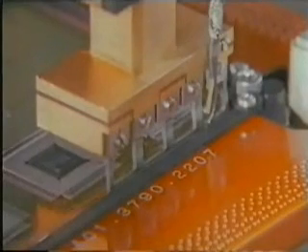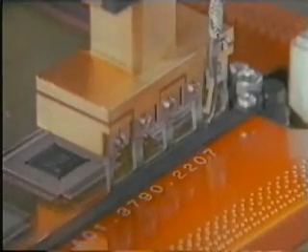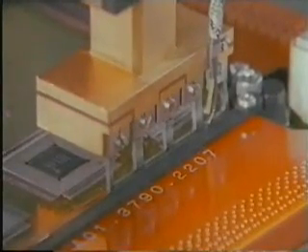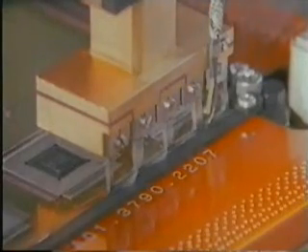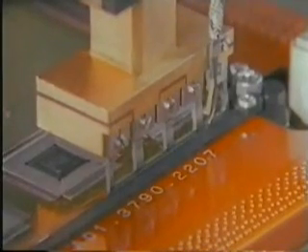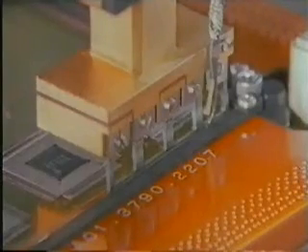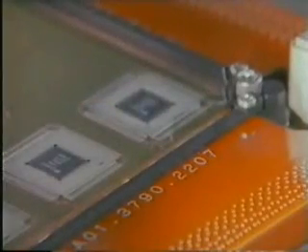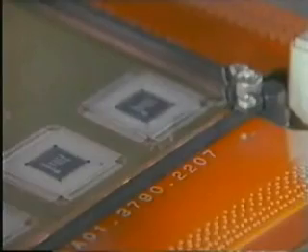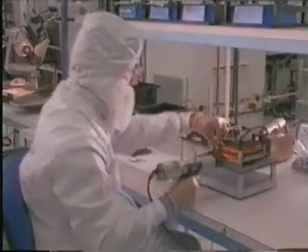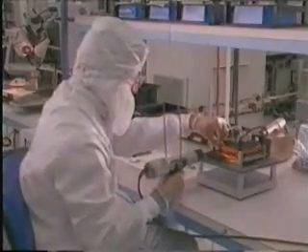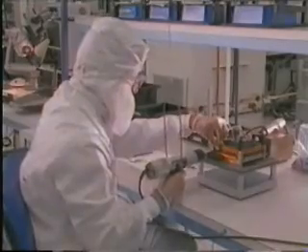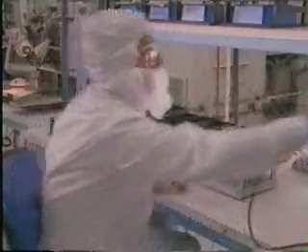Again, a thermode applies pressure and heat to bond the SignalFlex connector leads to the SignalFlex pad. Each one of these raised gold bumps connects to a signal lead on a chip. After washing and assembly, the raised gold bumps face upward.